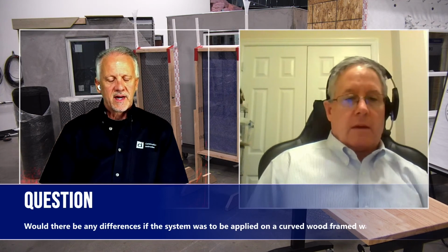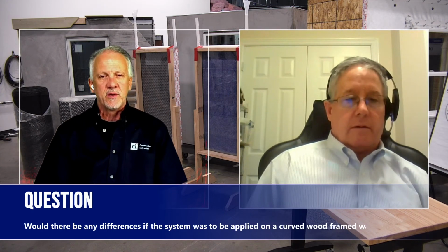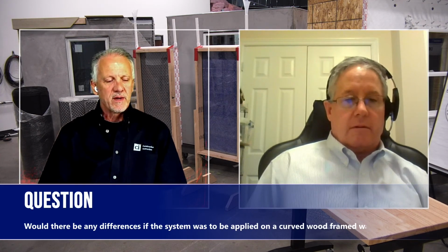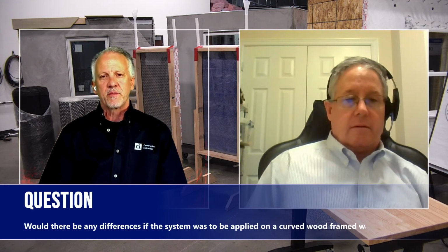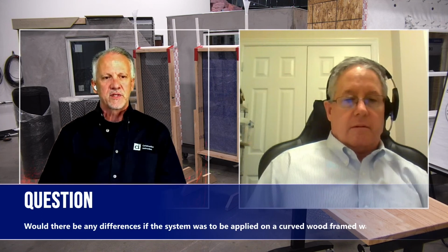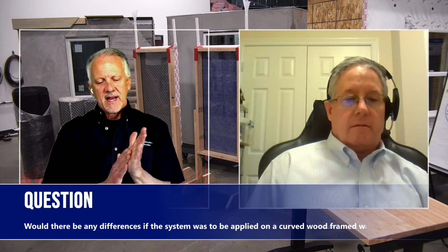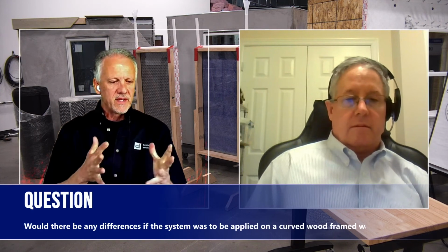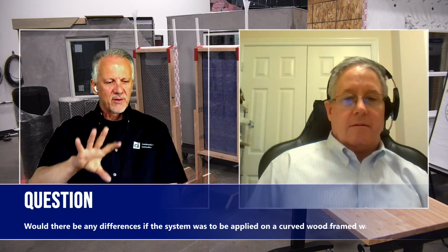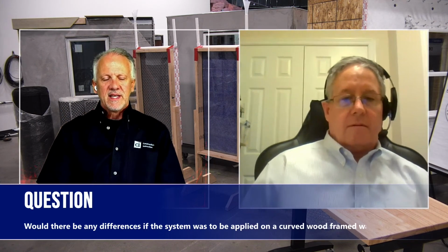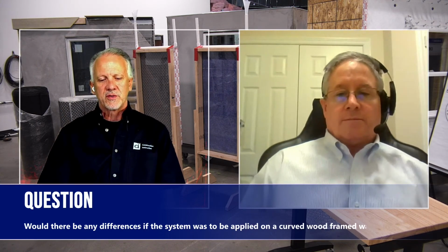Yes, expansion joints, and we see control joints are so seldom used anymore, and I think that they're pretty important. When you look at the lath and plaster bureaus and the stucco associations, they would really like to see a better use of expansion joints and the details for break lines. But I too often see that no one puts them in. So when you look at the spider cracking and the things going on, it's more difficult. So if we would see a few more control joints there in terms of expansion joints, that would sure be good. We're using full stucco applications.